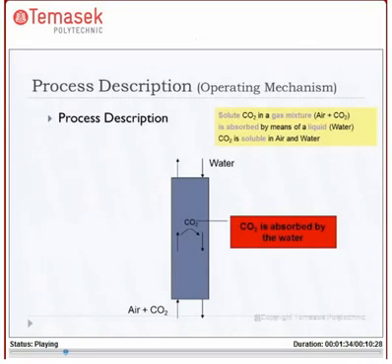As the gas mixture flows up the gas absorption column and the water flows down the column, the gas phase and liquid phase come into intimate contact, allowing the water to absorb the carbon dioxide. The final gas stream leaving the column has reduced amounts of carbon dioxide, which is the main aim of this operation.